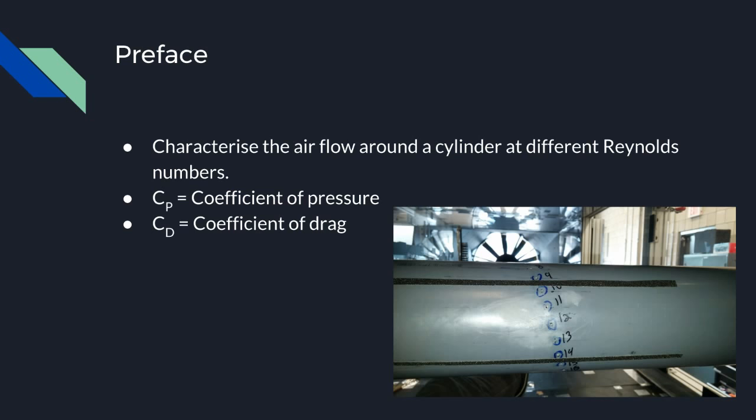around a cylinder. Setup. Inside the wind tunnel, there is a cylinder which is loaded with 24 pressure sensors. Each pressure sensor is separated by an angle of 15 degrees laterally. This allowed for pressure measurements around the entire circumference of the cylinder. By utilizing a smoke rig and laser sheet device, smoke was sucked into the test section and over the cylinder while being illuminated by the laser sheet on top of the test section for flow visualization.